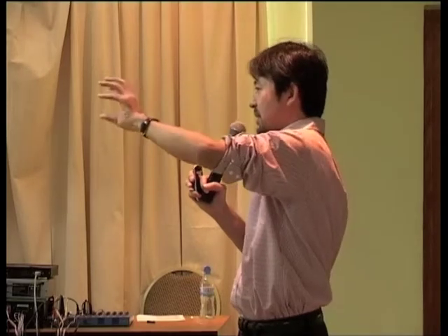This is reshaping if you use regenerators in the system. But an optical amplifier just amplifies the amplitude of the signal. So if you put a degraded signal into the amplifier, it just increases the amplitude, in proportion to the original input signal. That means the amplifier doesn't care whether the signal is degraded or not, it just amplifies. So you will see the same waveform at the output of the amplifier as the input waveform. So waveform distortion can't be restored by the amplifier, it just accumulates. Okay, an amplifier is just the same as the fiber, it just amplifies, nothing more. Okay.